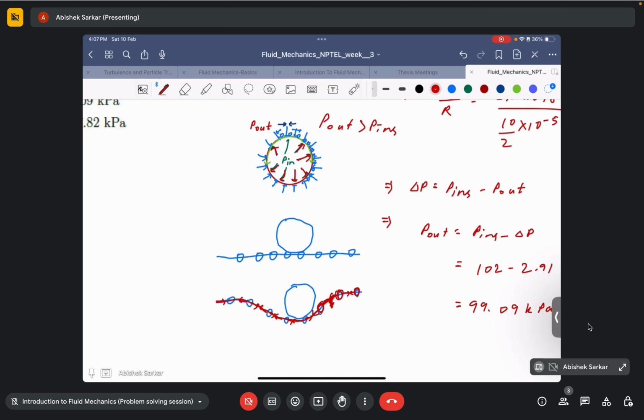And in equilibrium conditions, this pressure force along with the surface tension forces are balancing each other, and that's why the integrity or the shape of the bubble is contained. It stays the same. And that's why the inside pressure should be higher than the atmospheric pressure for the liquid bubble to coexist. Now you got it, right?